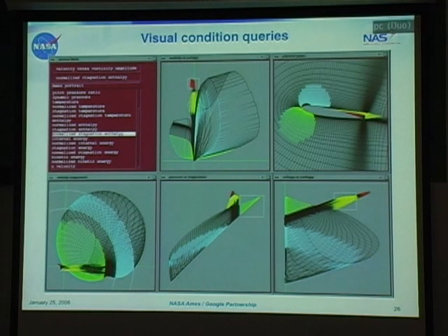So for example, in the lower left, we've embedded it in velocity component space. The free stream, or the undisturbed flow in this data set, maps to a single point here on the x-axis. Everything else is a perturbation of this flow caused by the wing. So regions of the flow farther away from the origin, which is here, are accelerated flow, and so we can select a range of those with this blue annulus tool, and you can see those correspond to the top of the wing. And flow, which is slower relative to the free stream, is in green. You can see that's below the wing.